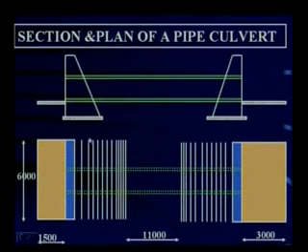Now I will explain to you part by part. This particular part is the apron which I was referring to. Apron or pitching on the upstream side. So can you get the data here from this plan? When we are making an estimate of the quantities of stone required for aprons or pitching on the upstream side, you can get the dimension from the plan here. See, this is the length of the apron, this is the width of the apron.